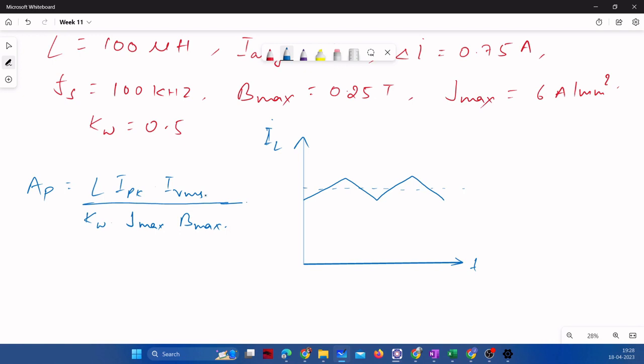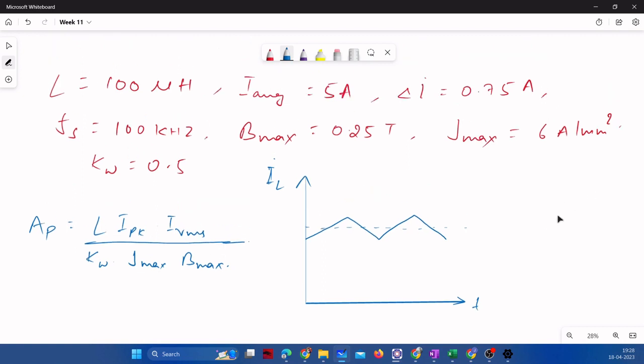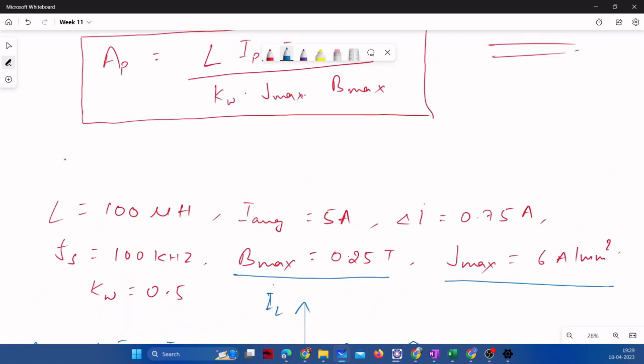Based on the Bmax, you can see the data set for which materials will be fine if you use this kind of flux density. You might refer to certain material data sets and see where it will be suitable, and please let me know in the next session in which material this maximum flux density will be suitable. And with Jmax, how much area of conductor you should use. There are two parameters that I am asking, if you could note it, please.